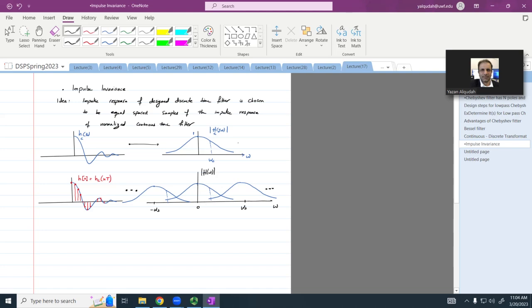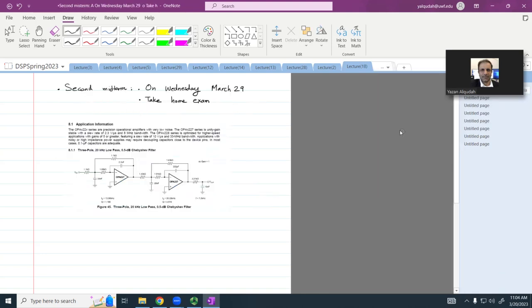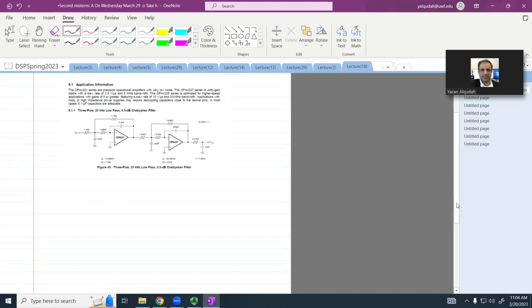I'm going to get the original frequency response, but also, in addition, I'm going to get this aliased version of that filter. Does that make sense? Because this graph is exaggerated. If this is repeated and the aliasing is less pronounced, then I have the filter shape that I'm trying to achieve. Does that make sense? So with that, we're going to continue our discussion using the impulse invariance method.